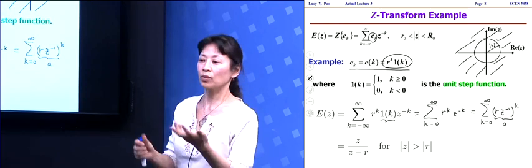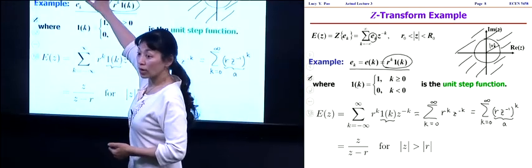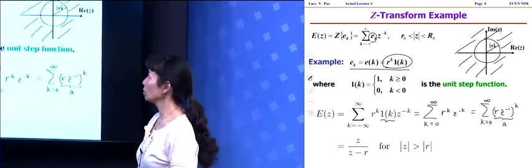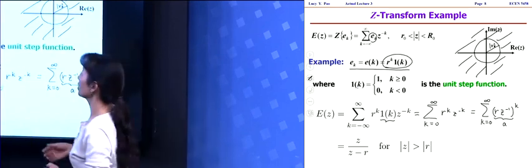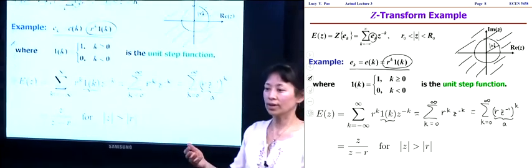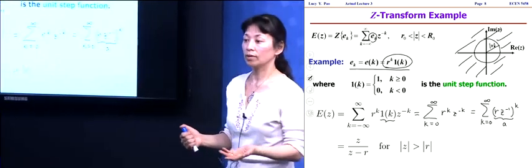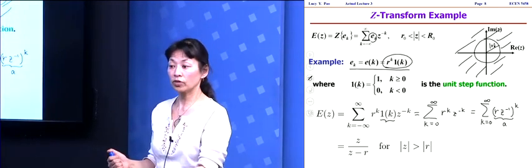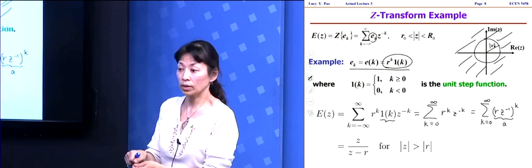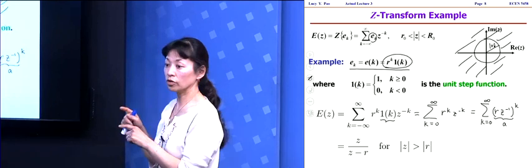Okay, so, I mean, that's like asking why is a Laplace transform defined the way it is. So this is basically a transform, okay, and all the transforms have their definitions, right? Like the fast Fourier transform, the Fourier transform, for instance. And they're really ways of dissecting a signal so that you can get at certain properties about a signal. So typically, it represents a complex frequency, right? And so when you're looking at a Fourier transform or discrete Fourier transform, the Fourier transform is effectively you're only looking along the j omega axis for a continuous time signal. And for the discrete Fourier transform, you're only looking along the unit circle.